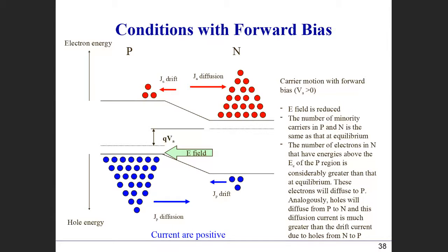Okay. So that's the forward bias case. And another thing you can clearly understand is that the hole diffusion current is in this direction, right? Because when this barrier is lower, holes move in this direction, so the hole current is in the same direction.